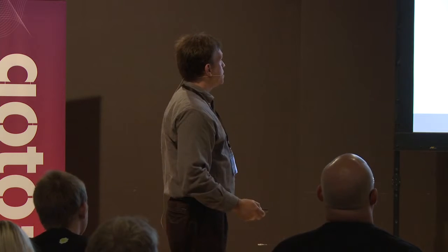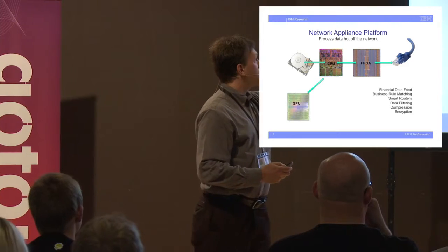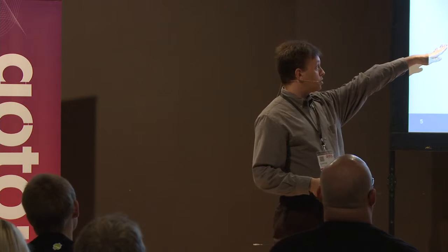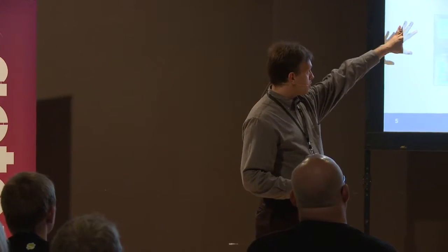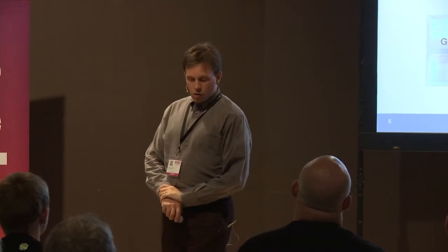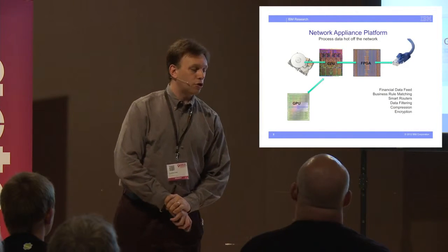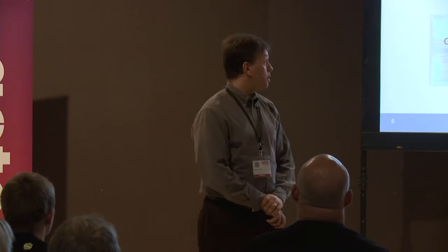When we start talking about FPGAs, they have other advantages which lend themselves to other kinds of deployment models. One which is very popular is using FPGAs in what we call a network appliance platform. You can plug your I/O, such as your Ethernet or serial bus, let's say your network, straight into the FPGA, and now you can design your hardware, so you can design your own network protocol to exploit very low-level structure. You don't have to worry about, say, running a custom operating system stack, and so forth. So you can get extremely low latency